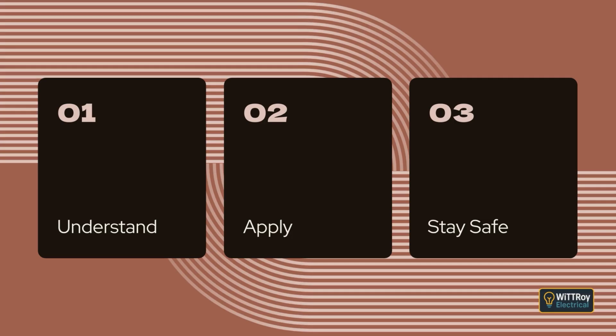Clause 3.5.3, Earthing conductor. This clause explains that the size of an earthing conductor must be chosen in accordance with Clause 5.5.3.3. The earthing conductor must be large enough to carry any fault current safely and maintain the integrity of the earthing system. Clause 3.6, Voltage drop. This clause introduces the requirement that voltage drop in a circuit must remain within limits so that equipment receives a safe and usable voltage supply.